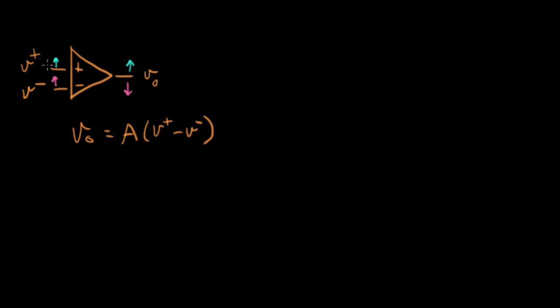Let's say that the positive input, the non-inverting input, went down this time. That means that V out will go down. And let's do the same thing for the inverting input. If the inverting input goes down, what does the output do? It goes up. It goes in the opposite direction. That's a way to think about this symbol when you see it on a schematic page: how do these signals translate through the device? Non-inverting signals go in the same direction. Inverting signals go in the opposite direction.